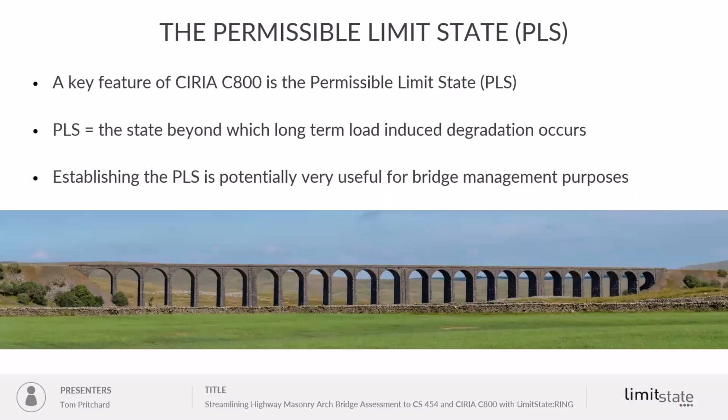So what is the permissible limit state? It's a key feature of CIRIA C800, and it defines that state beyond which long-term degradation of the structure is likely to occur. And establishing the PLS, like we say, is extremely useful for bridge management purposes. We know that the ultimate limit state doesn't really examine day-to-day behavior, just the extreme of the collapse state. So it's useful to understand what the difference between that and the permissible limit state is. And there's two things in particular that we're looking at.